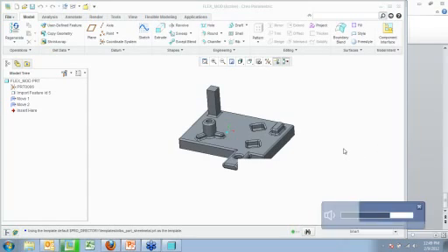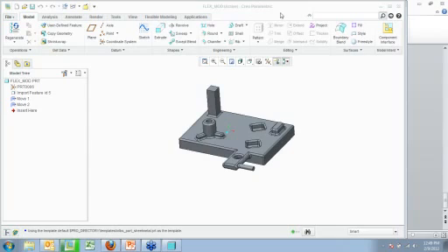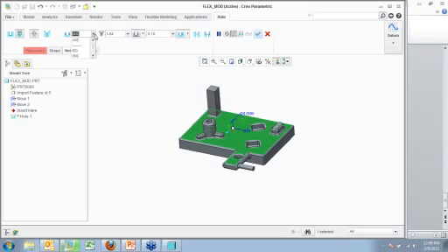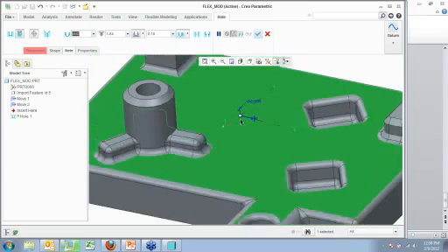He typed it in. Does Creo Parametric offer a threading profiling tool, i.e., the ability to cut threads? That's the same as it was in Wildfire 5 and I believe Wildfire 4 and maybe even Wildfire 3. If I want to come in here and create a hole and put cosmetic threads on it, I've got my UNC and UNF and ISO, and I think you can even add in NPT tapered threads. We used a lot of pipe threads in my last job. I can't remember if that was a custom thing we made or something we downloaded. And it'll create cosmetic threads.